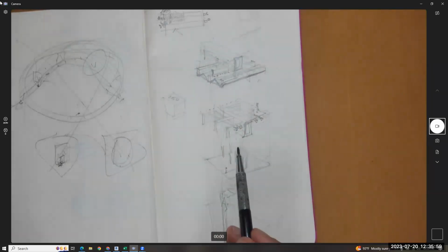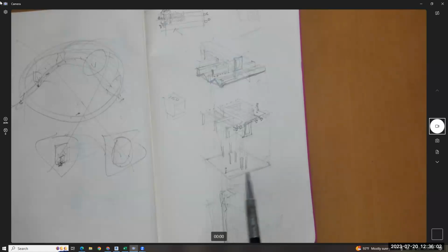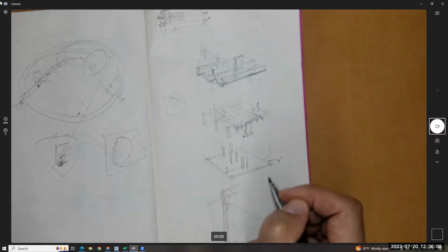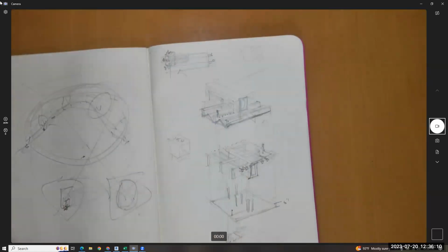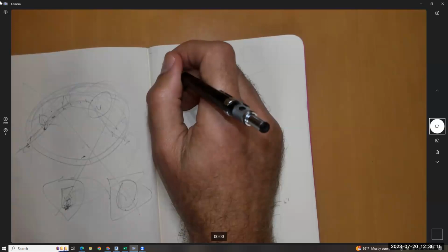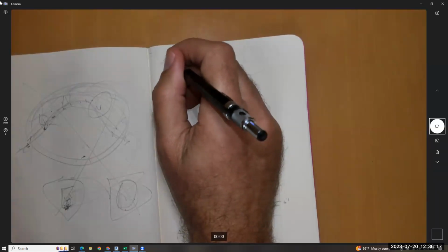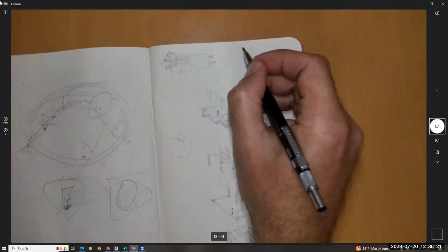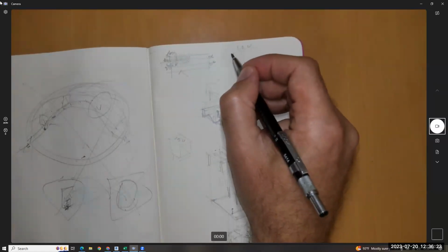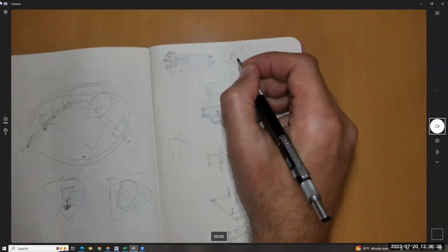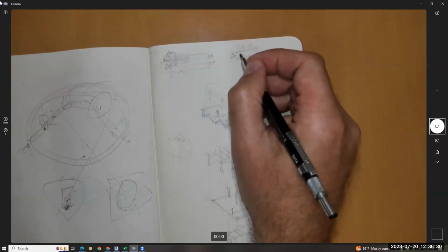Let's figure out what just this basic floor down here weighs, and we're going to be really cheap about it because I know it's hollow and it's got some structure. We're just going to pretend this is a 6-inch deep slab. Let's make it easy. Let's say the trib area is 100 feet by 60 feet. So that's 6,000 square feet.